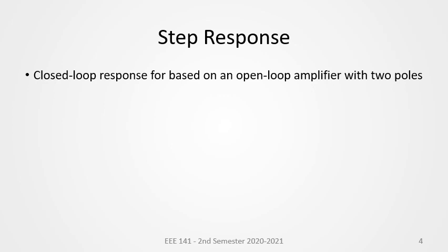The conclusions that follow should therefore approximately hold for systems with more poles as long as the third and latter poles have little effect on stability. The same concepts must be reviewed or verified if the third pole or some other zero is affecting the phase margin of the system.